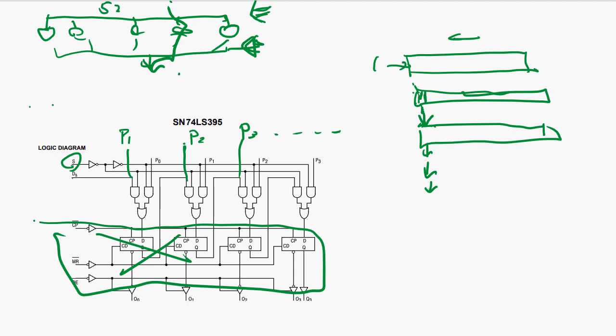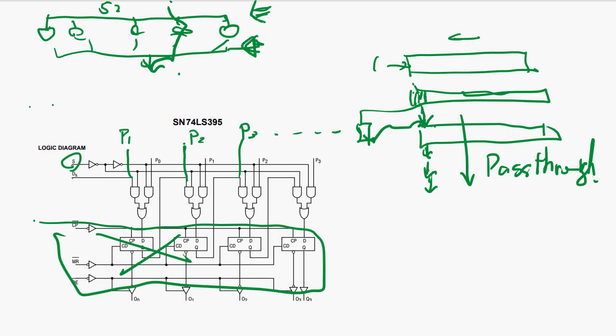Once this 1 is captured in the flip-flop, then this flip-flop stays on, so it's all passed through until we find the leading bit. Shift one bit, and the shift one bit is just in the CMOS 2 gate. So data passes through this leading bit detection.